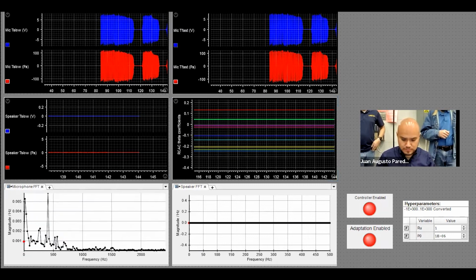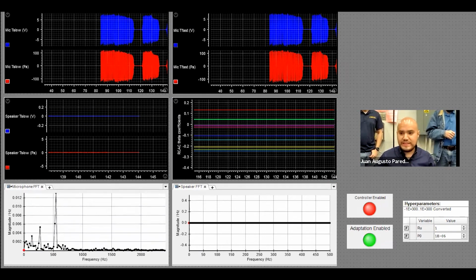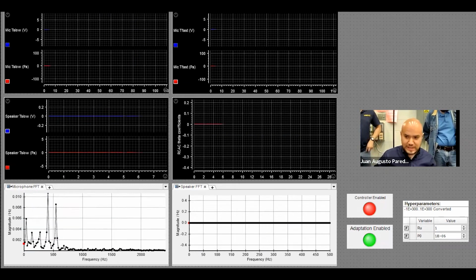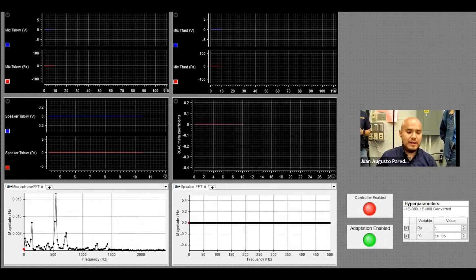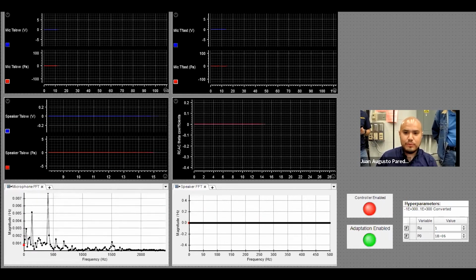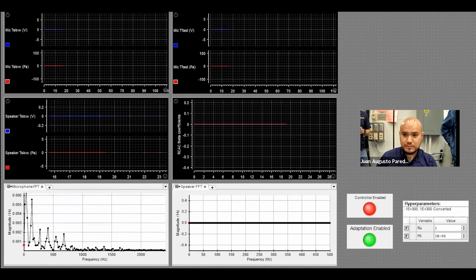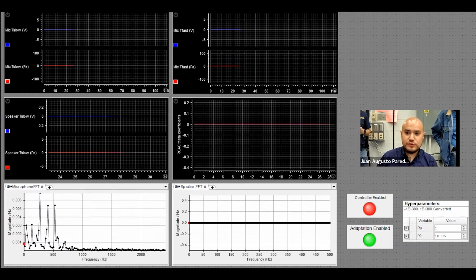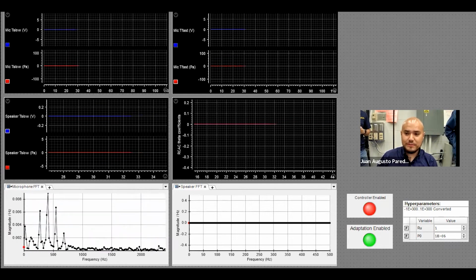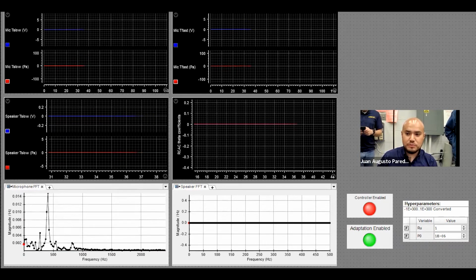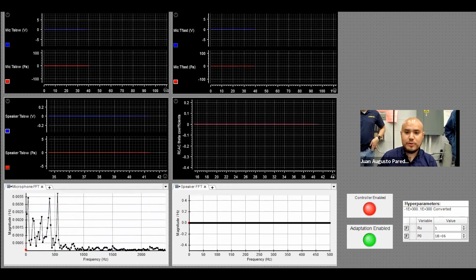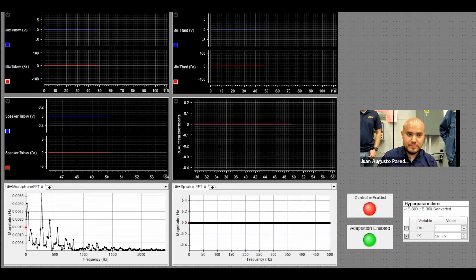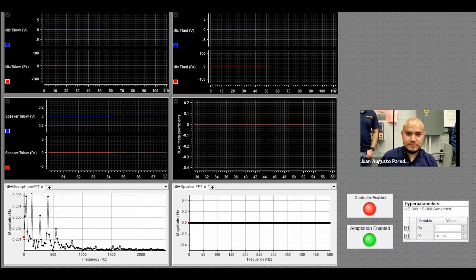Now for the next test, we'll do a dynamic test in which we will allow RCAC to stabilize at a higher point of the coil, and then we'll bring the coil back to the point of easier oscillation. We will stop adaptation, and then we will disable the controller to allow the oscillations to form up. We'll enable the controller with adaptation disabled, and we will show that the controller obtained in the previous position will not work on this new position due to different operating conditions. Then we'll allow adaptation to start once again, and we'll see how RCAC can readapt its controller coefficients in order to once again yield a set of controller coefficients that suppress the oscillations.